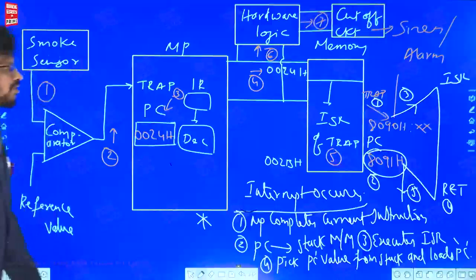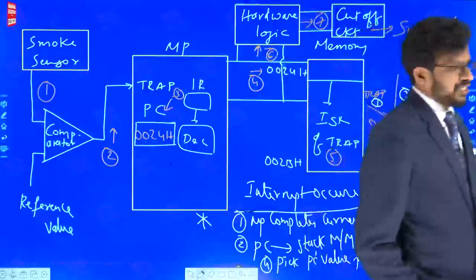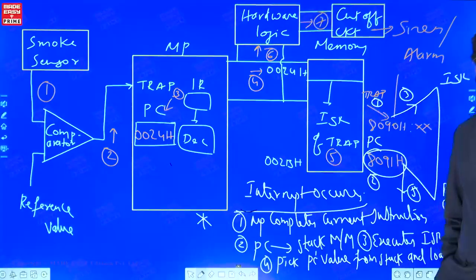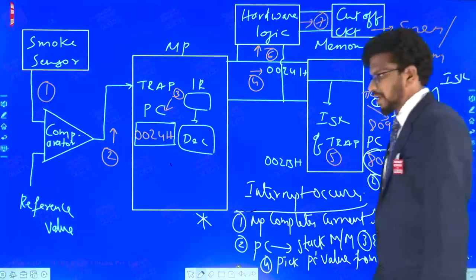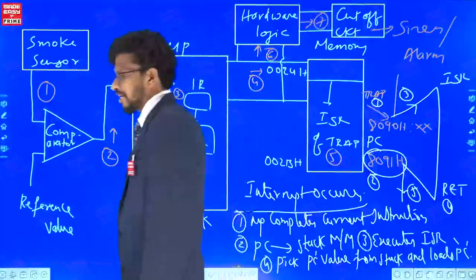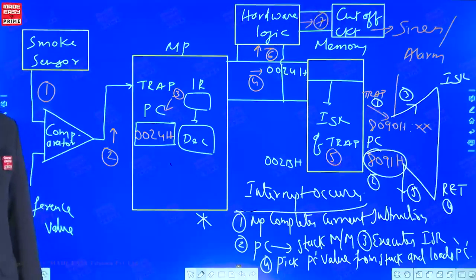You can write one note. In case of vectored interrupts, there is a built-in logic within the processor such that the vector address of the interrupt is automatically loaded into the PC.